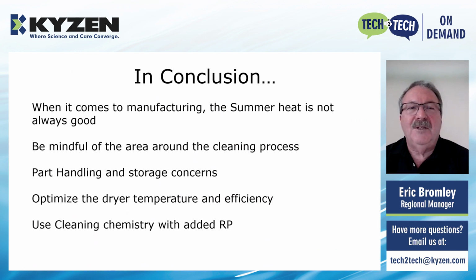So, in conclusion, when it comes to manufacturing, the summer heat is not always good. For some parts of the country, it's nice to have the summer heat back, but with it comes a lot of problems, and rusting can be one of them. Be mindful of the area around your cleaning process. As I mentioned, the open doors and the fans and the cooling and the passivation lines and the acid dip lines, those can cause quite a bit of moisture to be put into the production area,